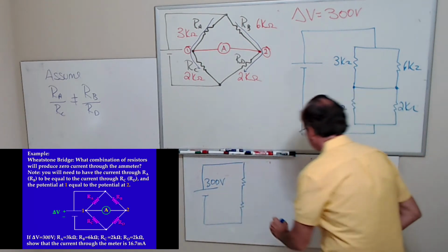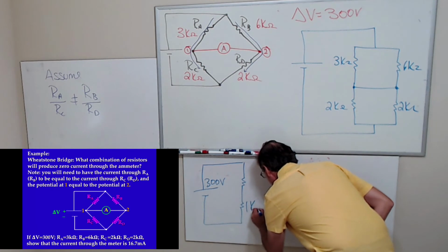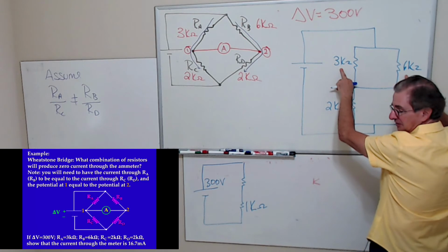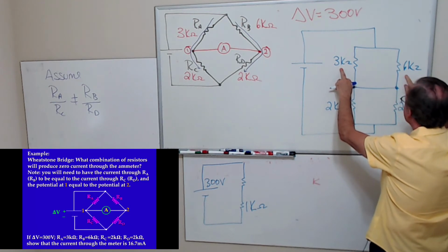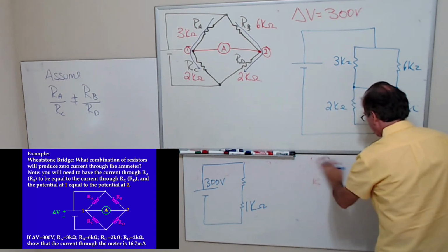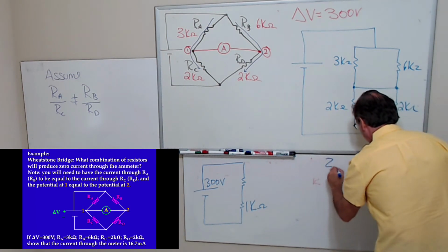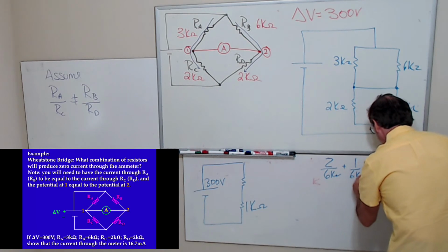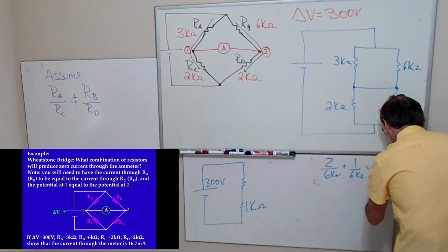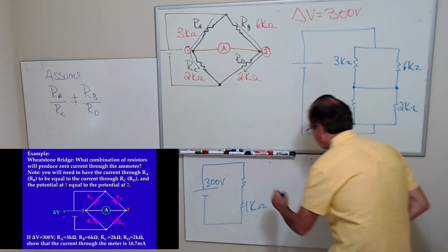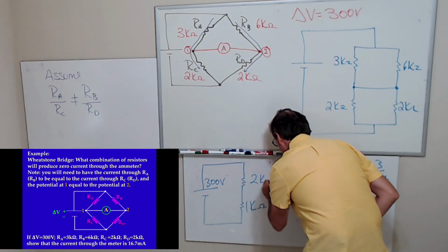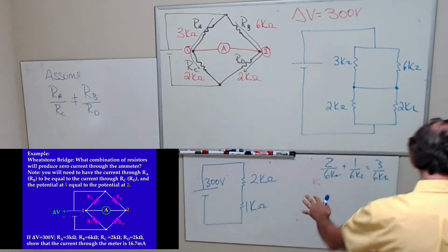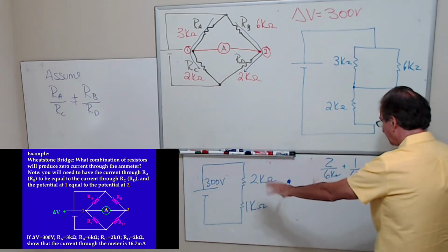These give 1 kilo ohm. And do I have to do the math for this one? 1/6 and 3/6? I get a common denominator. I take the reciprocal, I get 2 kilo ohms. Okay, so my total resistance in my circuit is 3 kilo ohms.